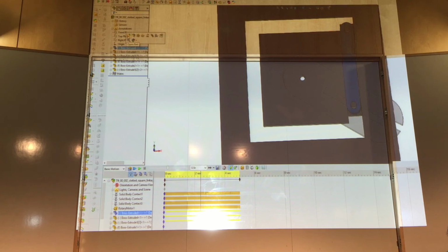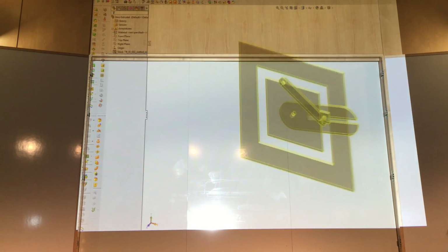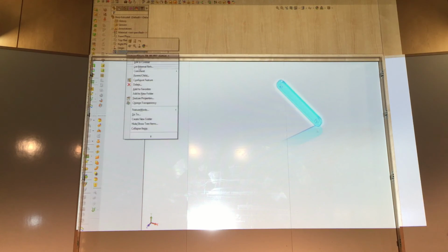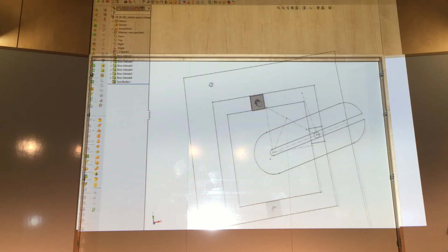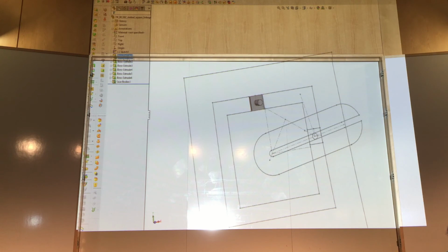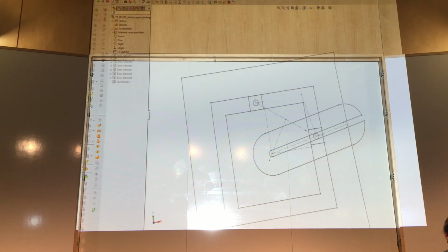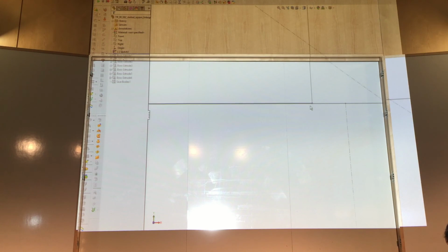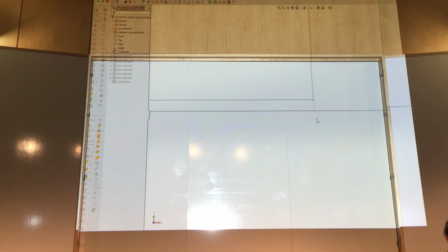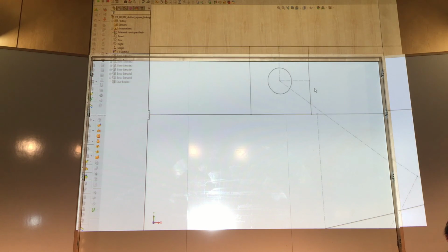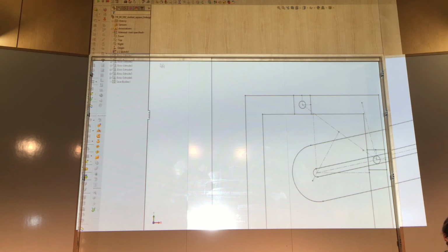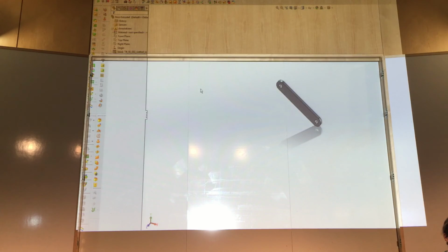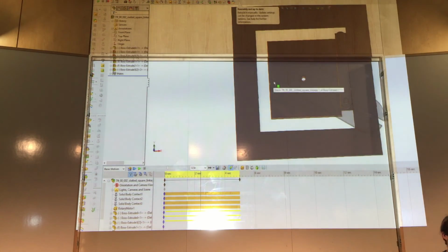So if I open this part, edit context, I drew out my interface. Again, everything is drawn out as this one sketch, and I even have the little gap in there, so you actually need a little tolerance so that the thing will fit. Draw in all of those little details, and then you can blast through making a bunch of bodies, export them all as saved bodies, and then generate your assembly, where you can do your simulations.